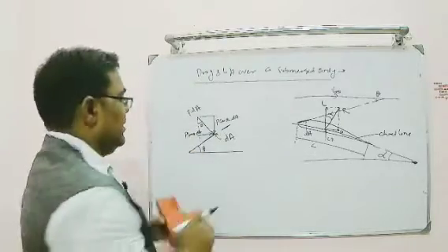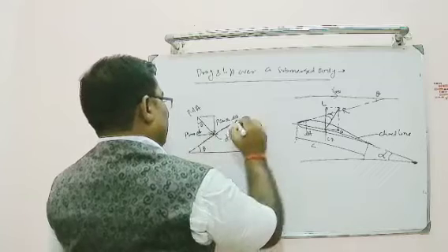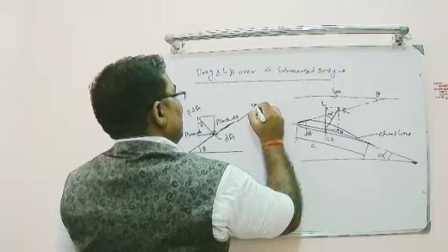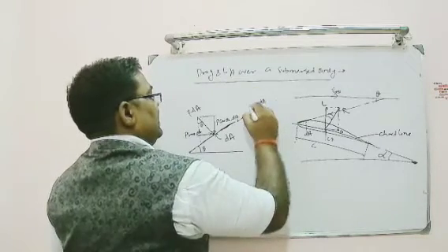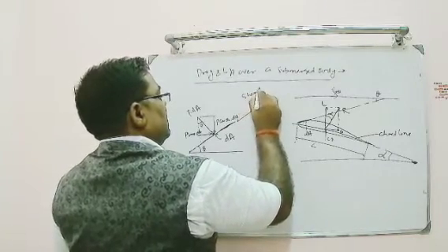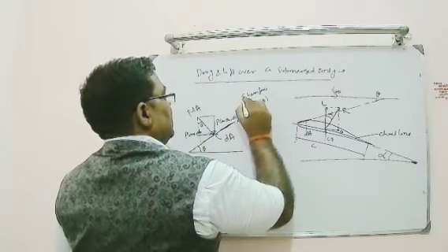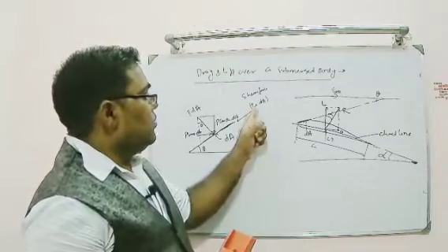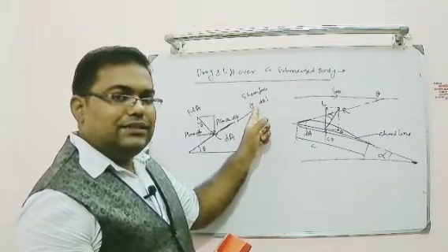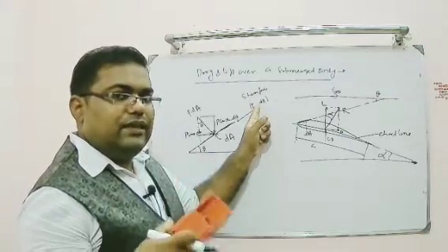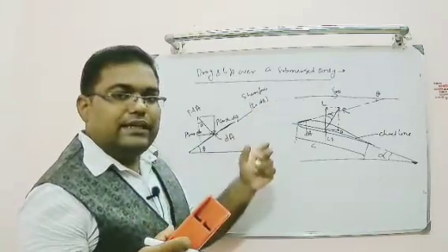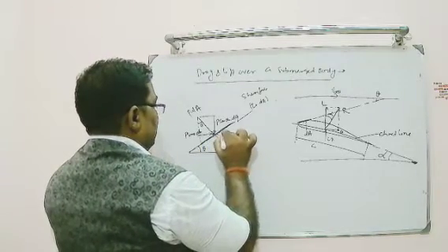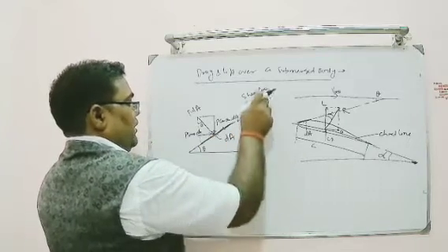Now what about shear forces? The shear force will act parallel to this direction. This is the shear force direction, which I have mentioned as tau naught into dA. Clear? Tau naught is shear stress, and shear stress is shear force by area. So shear force is equal to tau naught into dA, where dA is my elemental area which I have considered for the study, up to here.